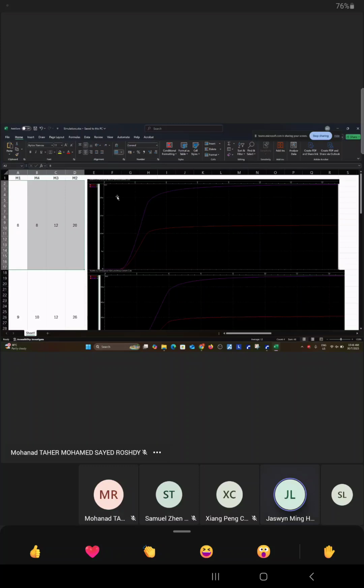Yeah, 50 micro is your base, your reference current, right? Then once you mirror it to your main op amp, you actually multiply it further, right? Yeah, I think you multiply too much. Actually, 50, I would say, is a good spot for your current bandgap. It's very good already. Even if you go to, let's say, this is 12.5, right? Yeah, 12.5 is even better because it's more stable. Then later on, you can multiply even further, since you can adjust the width of your MOSFET. Then you just keep everything at your current bandgap to your first branch of the current mirror.